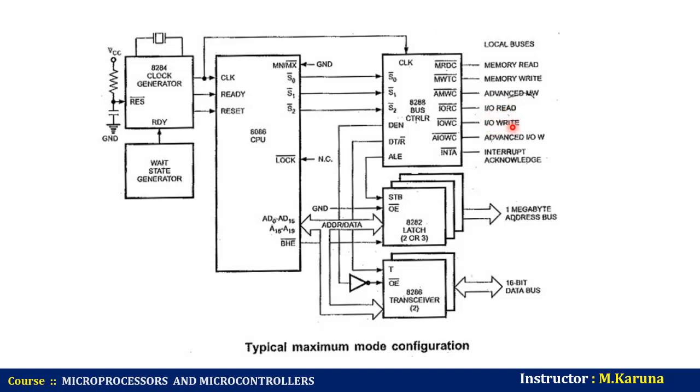In this case advanced write commands are also present. These advanced write commands are activated one cycle earlier than the normal write commands. Processing becomes a little faster due to the advanced memory write command and advanced IO write command. These advanced signals exist only for write commands.